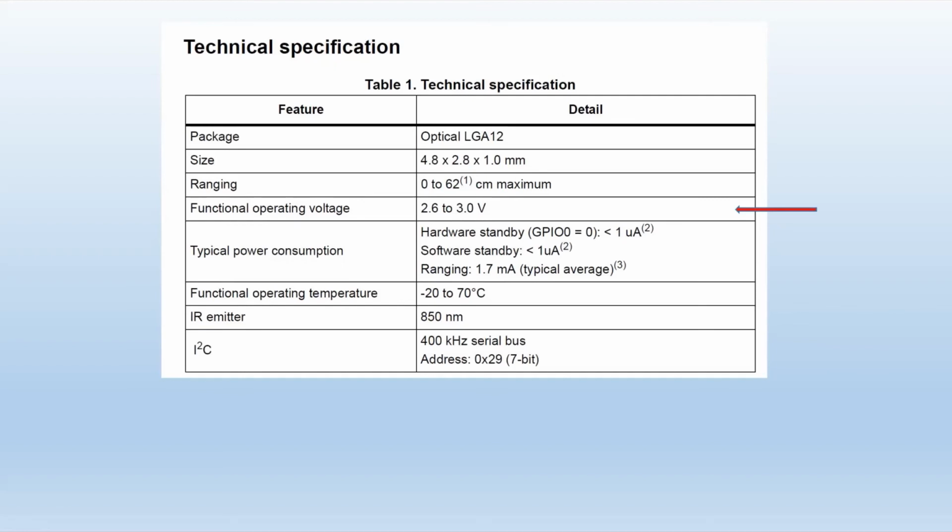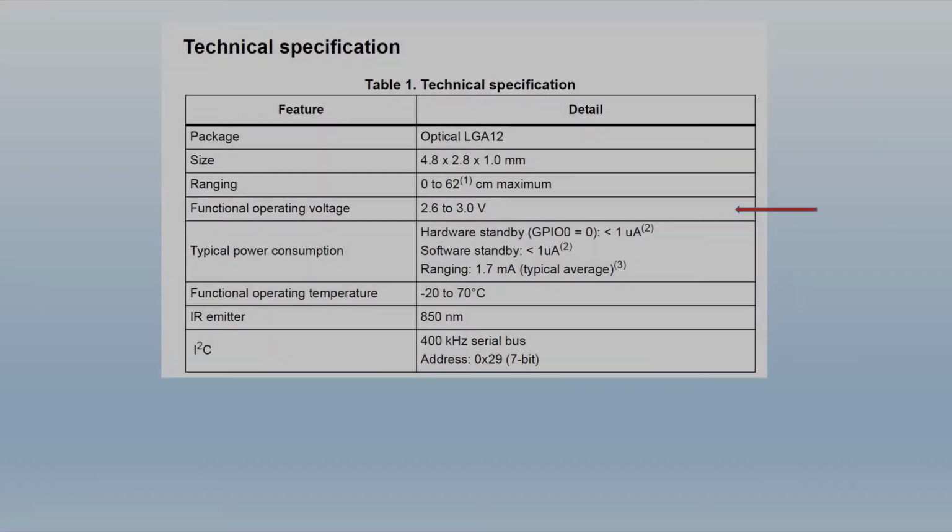And we want to interface this to the Arduino. This can cause problems for us. The module itself wants to run on 2.8 to 3 volts for power. We can overcome that with voltage regulation and so on. That's easy. But the data going between the module and the Uno or the Nano, whatever, are different voltages.